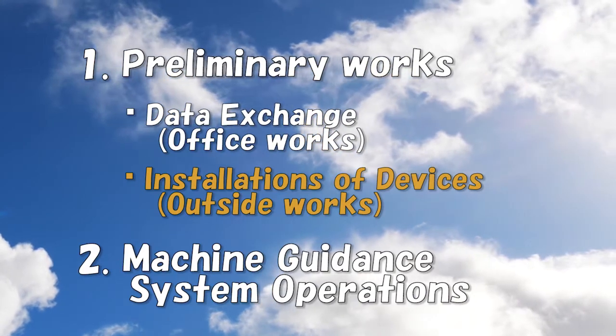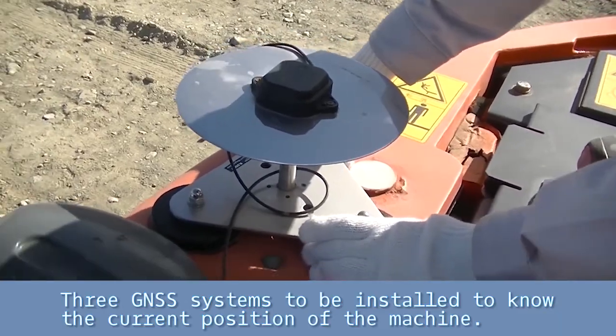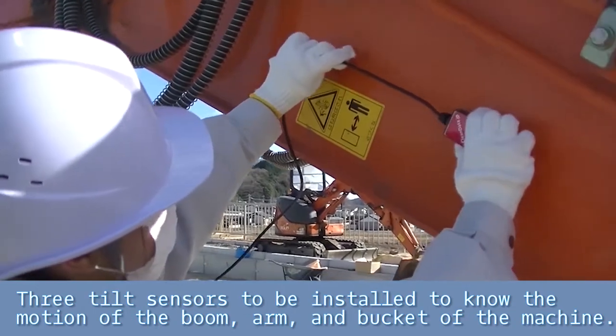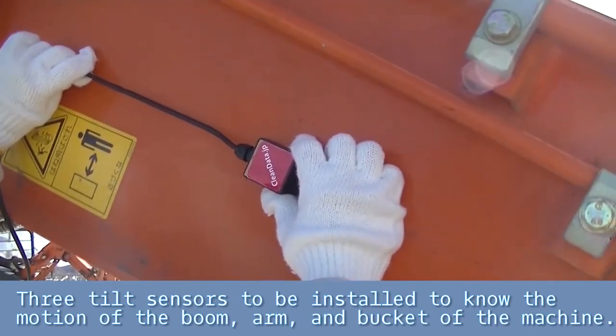Next, let's perform installation of the sensors and their calibration. First, 3 GNSS systems are installed to know the current position of the machine. Next, 3 tilt sensors are installed to know the motion of the boom, arm, and bucket of the machine.